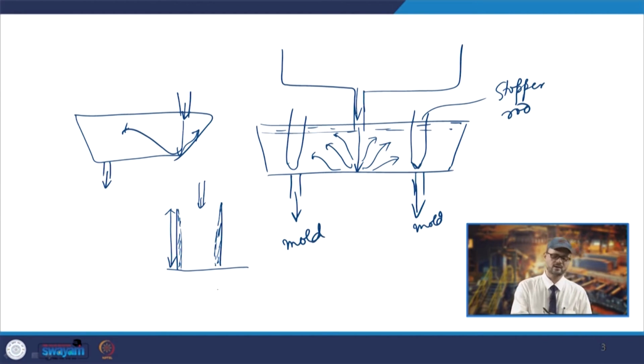it has to further come and move on the rollers, and finally it has to be in the horizontal direction. So, there is a large amount of pressure of the liquid steel, ferrostatic pressure. So, you ensure that cooling is such that a skin of adequate thickness is developed at the end of the mold. That has to be ensured. That is the requirement in the case of the mold.